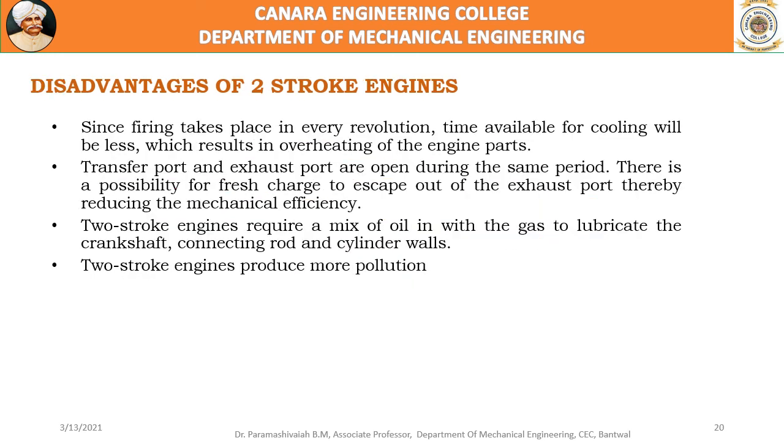Disadvantages: since firing takes place in every revolution, the time available for cooling is less. Cooling is a problem because there is continuous power stroke, burning of fuel, in every rotation of the crank. Therefore, the cooling time available is less, which results in overheating of the engines. The transfer port and exhaust port open during the same period. There is an overlap during which both the transfer port and exhaust port are opened.